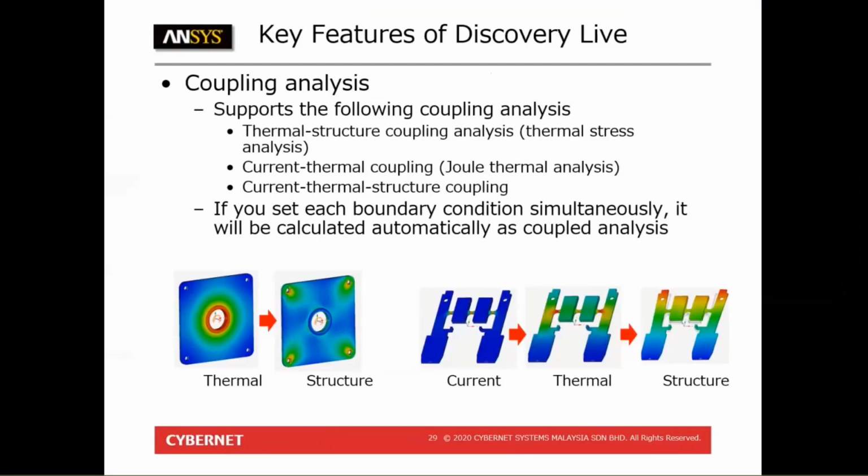When you set the boundary conditions simultaneously, say for example, you apply a thermal load on the center of this plate right here, and then you apply a fixed point on this hole right here, which basically sets a thermal structure coupling together in the boundary conditions, the system will automatically detect it and set that simulation as a coupled analysis.